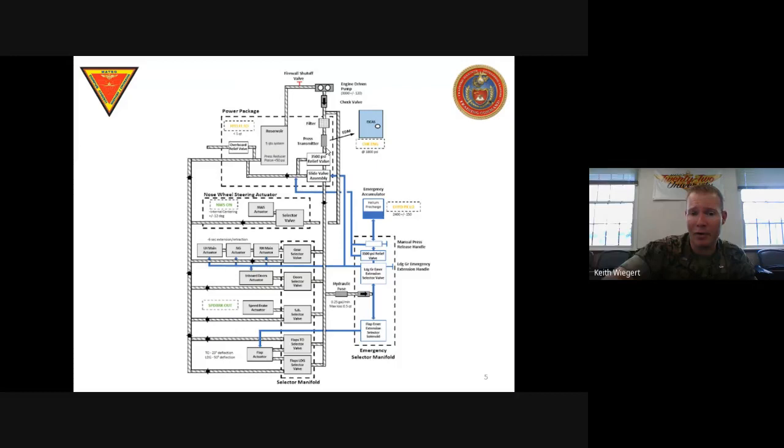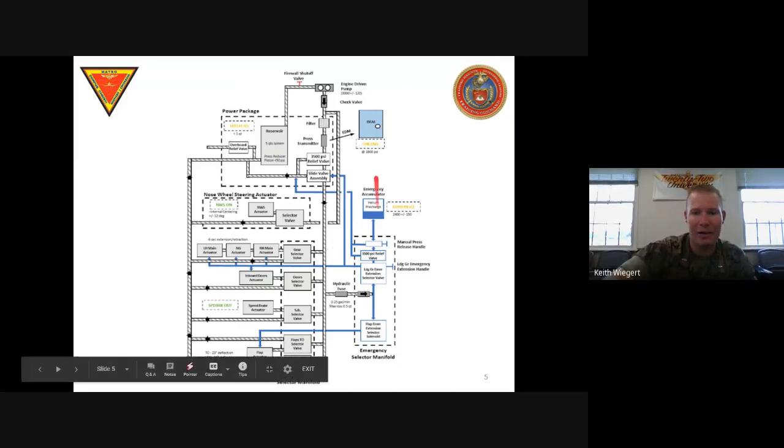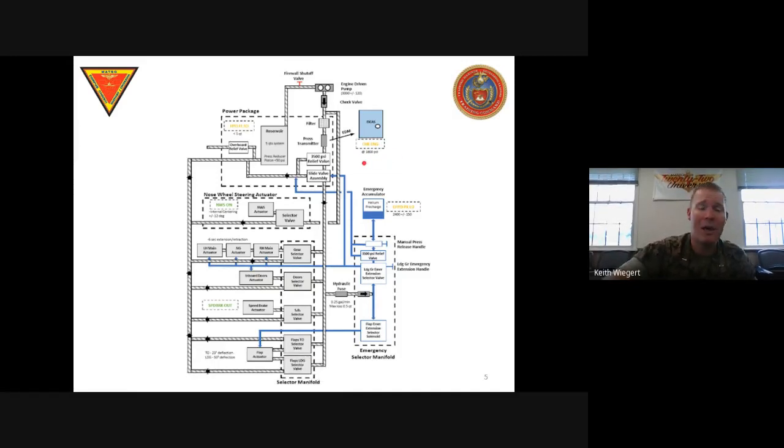Then we're going to come to the pressure transmitter. The pressure transmitter is going to pick up pressure data from the fluid, and then send that over to the ICAS display and display it on your hydraulic pressure gauge over there, right? Remember, we are going to get that check engine light if we get pressure less than 1,800 psi, right? But we also get the check engine light if pressure is greater than 3,500 psi, because you never have a hydraulic pressure low. It's always check engine for above or below because it could be one or the other, right?